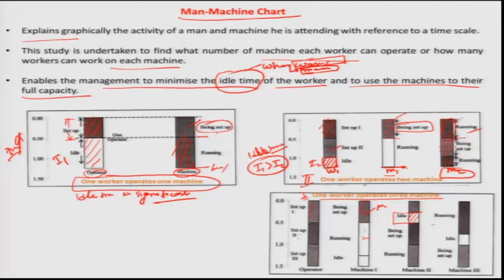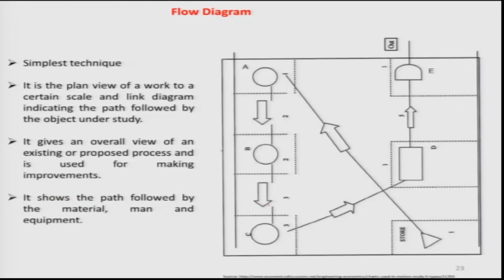Okay. After that, the worker will go to machine M2 and start some pre-processing so that machining will start. In between, the operation of M3 will complete, and it will wait for another operation, because the worker is busy in M2. After that, M2 will finish its work and he will go to M3 to set it up for another operation. You can see that for each machine there will be some idle time, but the worker will always be busy. This kind of arrangement is made in industry so that idle time can be reduced and finally productivity is improved.